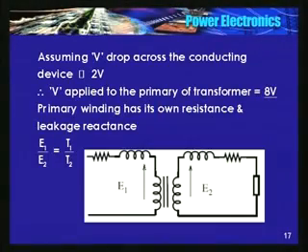So the peak of this voltage, I am neglecting the drop here, you require 230 into root 2 here. So 230 into root 2 is the voltage that is required here. I am assuming that this voltage will appear here, neglecting this drop. So what is the turns ratio? 7 here, 230 into root 2 is somewhere here. So the turns ratio is of the order of 47.